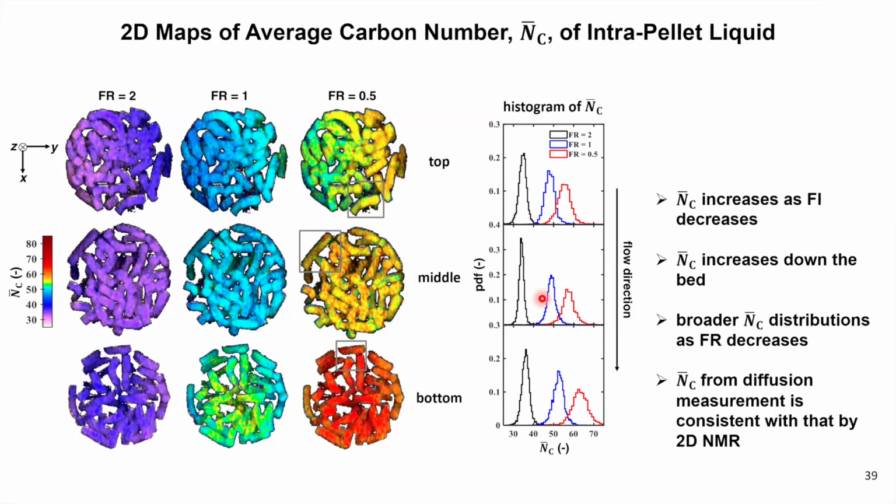And so there is a limited time over which you can do this, because you're still doing the spatial encode in the XY plane for every image. If you have very high X or Y velocities, then you will get fluid that begins to migrate from one pixel to another. You can see a bit of that happening, but from the velocity you can calculate how significant that effect is, and typically, over about 100 milliseconds, this was not significant.